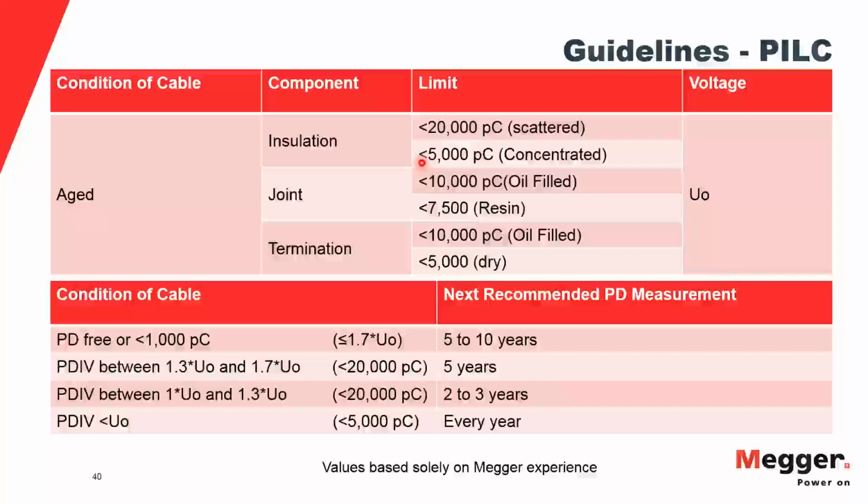That's a very good question, and ultimately that is the whole point of this webinar, to illustrate the point that if you're only using VLF sine technology for partial discharge testing, you may miss partial discharges, and you would never know. There's no way for you to know that if you're only using VLF sine. So how do you cope with it? You cope with it by using a different technology. You use damped AC or cosine rectangular. You use something that's closer to power frequency.